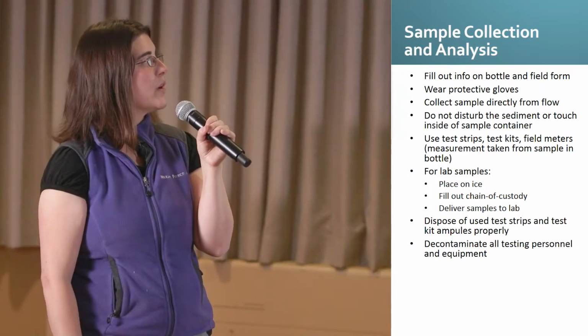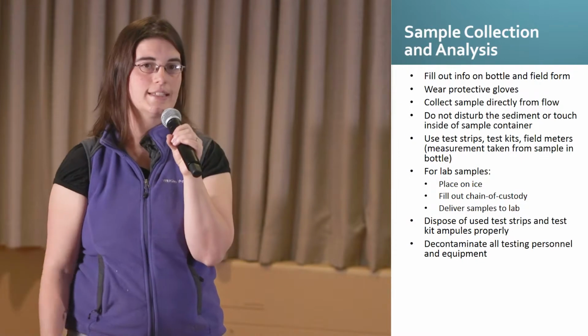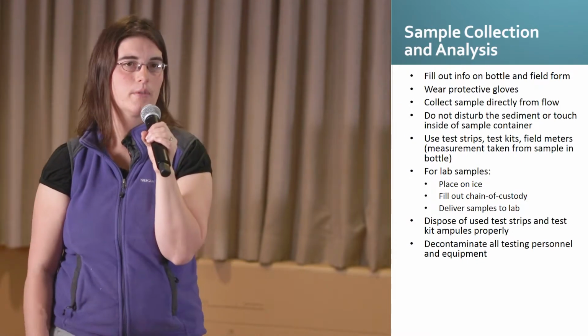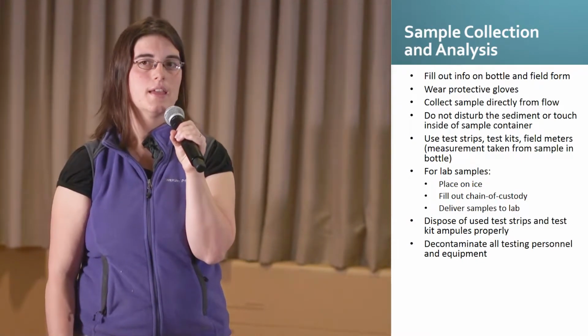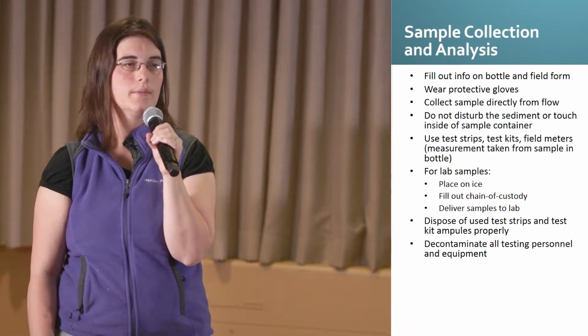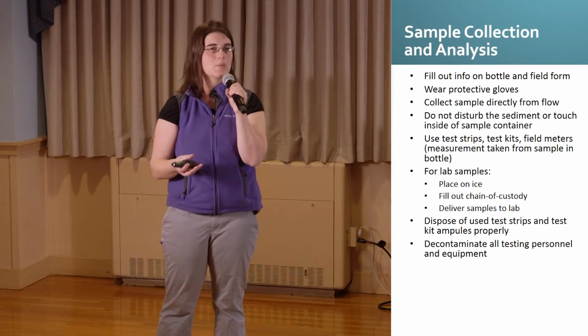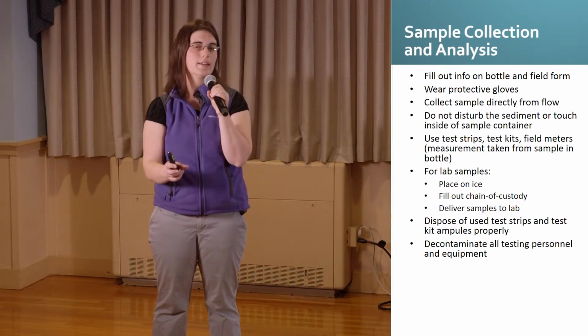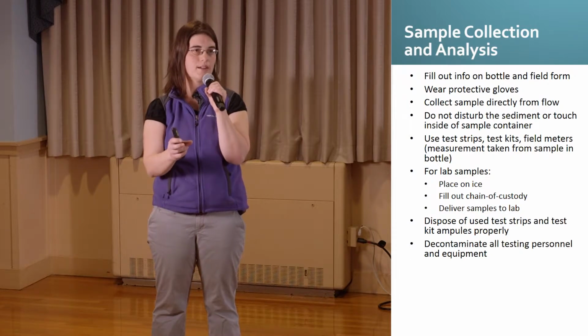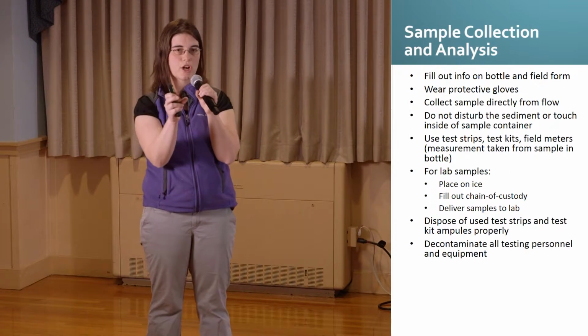You want to wear protective gloves when you're filling your sample, so you're not contaminating the sample itself with anything that may be on your hands. Some tests have a higher susceptibility to being contaminated. And when you collect the sample, you want to try as much as possible to get flow directly into the sample bottle, a representative flow, usually from the center of the discharge.